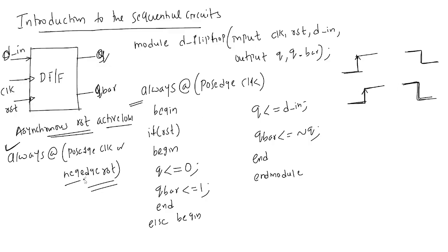That too you are using active low reset. Why not active high reset? Active high means that when it is going from 0 to 1, this is deactivated and this is activated. So you are operating your device when the reset is high. That means you are applying extra power to operate your device in reset mode.